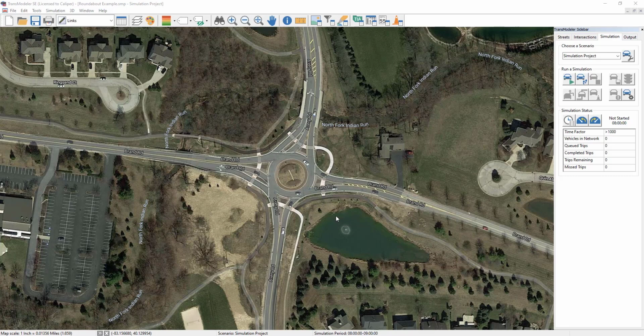First, add the cross-street links and node as though it is a conventional intersection. The road class assigned to these links in the initial step should reflect that of the approach streets, not the roundabout class.